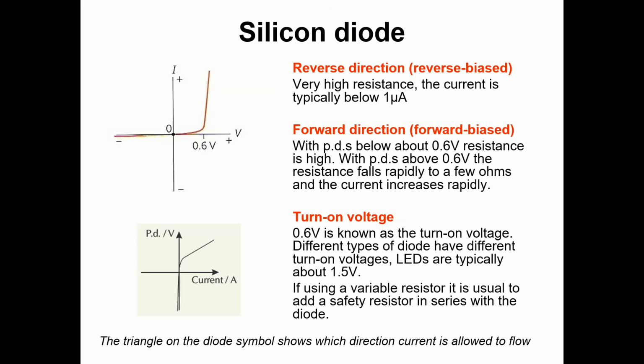Oh yeah, worth adding. But the thing about if you're using a variable resistor, worth adding a safety resistor in series with the diode, because that's usually worth a mark in a long answer question.